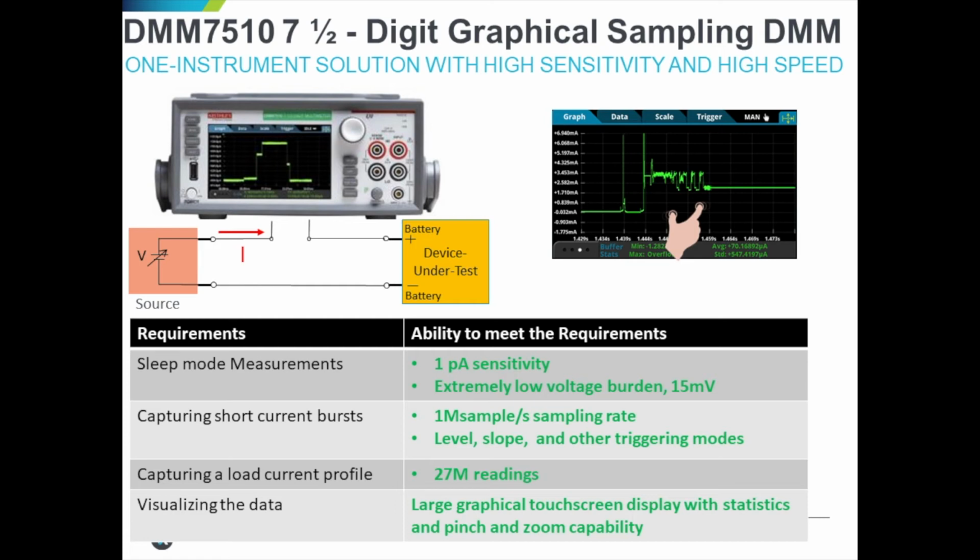Its superior accuracy, particularly as it relates to capturing sleep mode measurements, has a 10 microamps range, and a DC current accuracy of 75 ppm of reading and 30 ppm across the range. Additionally, like a good scope, it has great triggering options to review all possible current burst modes, whether it's a rising or falling edge, as well as being able to set and use your cursors as a part of making your computations, all of which help, again, correlate all phases of power consumption and measurements.